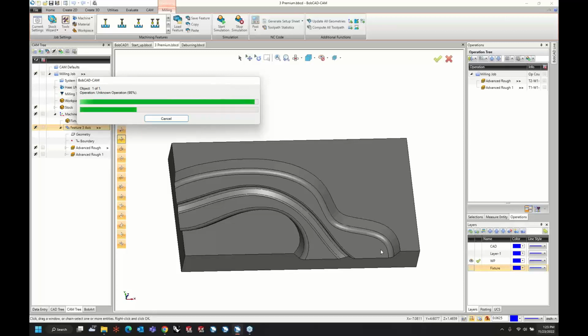And while this is calculating, one of the things about this particular shape, when we get to look at the finishes: if any of you have already used some of the 3-axis or have been to any of the other events, we usually go through what those toolpaths do, kind of how they function. And if you've watched one of those, you'll know that a lot of those toolpaths really don't cut this type of organic shape very well. Sometimes you'll get some odd toolpath patterns, some weird cusp heights. You have tools to kind of help mitigate some of that, but it can be quite difficult at times.